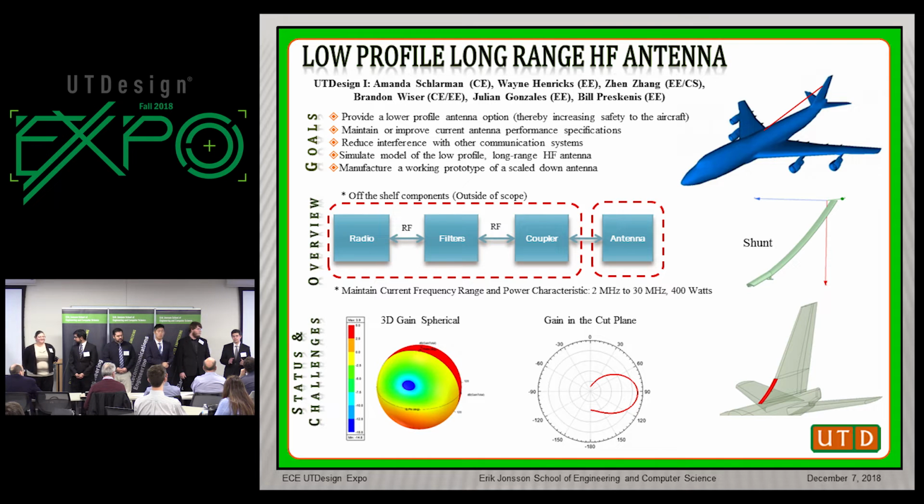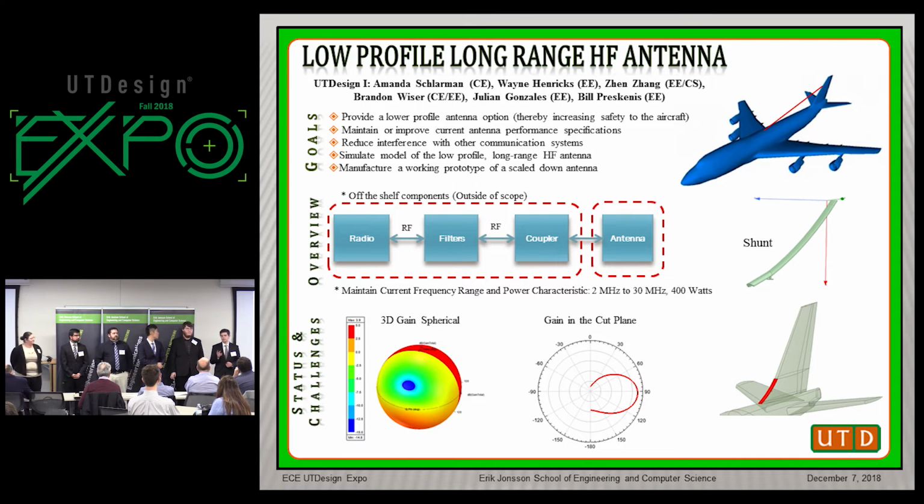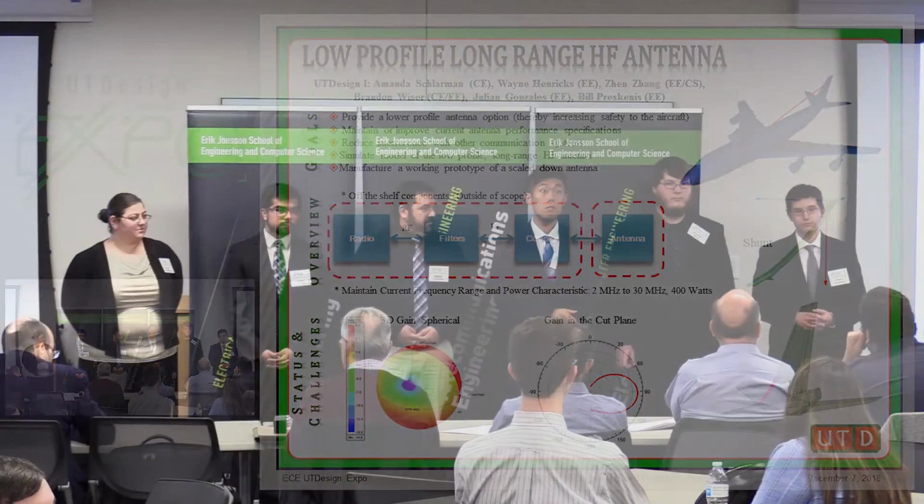I'll be putting the scale models we make into a wide open area and taking measurements from around it with an oscilloscope, while broadcasting a constant waveform on the antenna, and then compare those results to what we would expect from ANSYS. I will also be putting the models through a wind tunnel so we can compare the low profile of each antenna. Are there any questions?